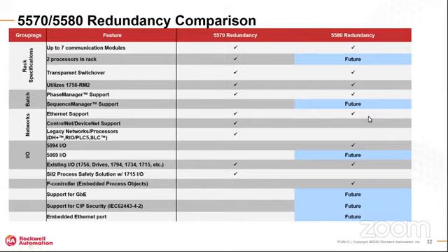Again, EtherNet/IP support, that's all there. We will not be supporting ControlNet, DeviceNet, as I mentioned, or the legacy network protocols or processors in an L8 style control. The 5069 with that unicast connection will be in a future release. As you guys are aware, if we're looking at an L8, they support the 5094, which is Flex 5000, and also the Compact 5000. You are not able to communicate with an L7 in the first place. So Simplex still works, but if we're looking at redundancy, the 5069 will be a future addition.